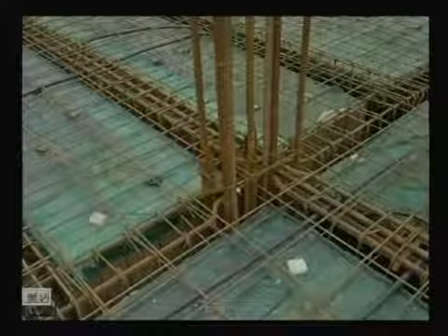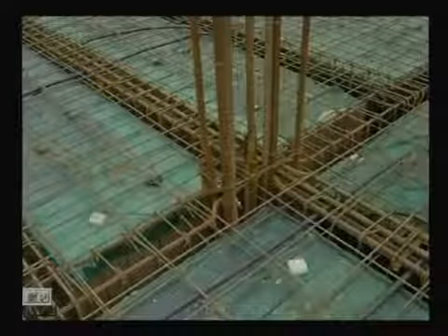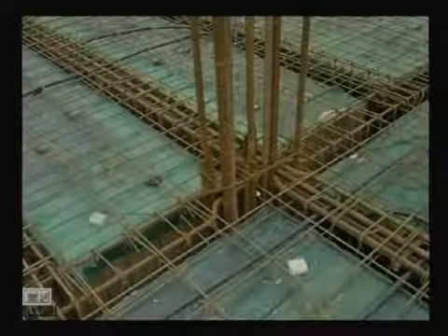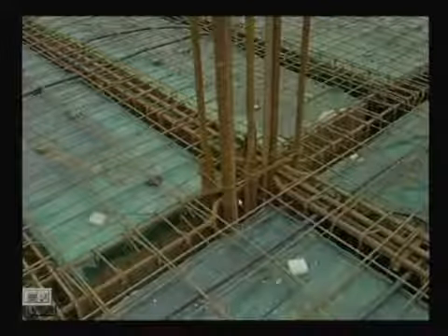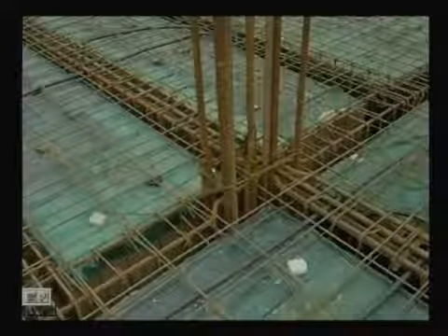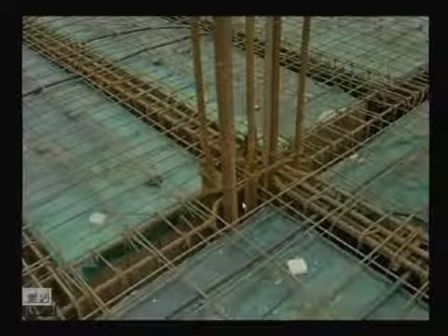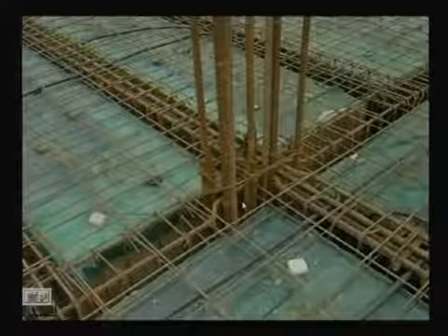When you are talking about reinforced concrete, you also have to consider what gaps should be provided here, these gaps. Whenever you are giving the reinforcement detailing, you have to take care whether you have sufficient gap for your coarse aggregates, because it is dependent on the coarse aggregates.